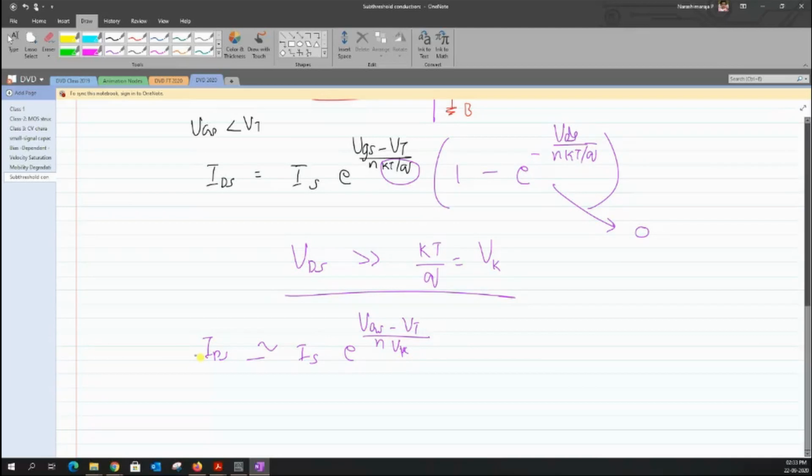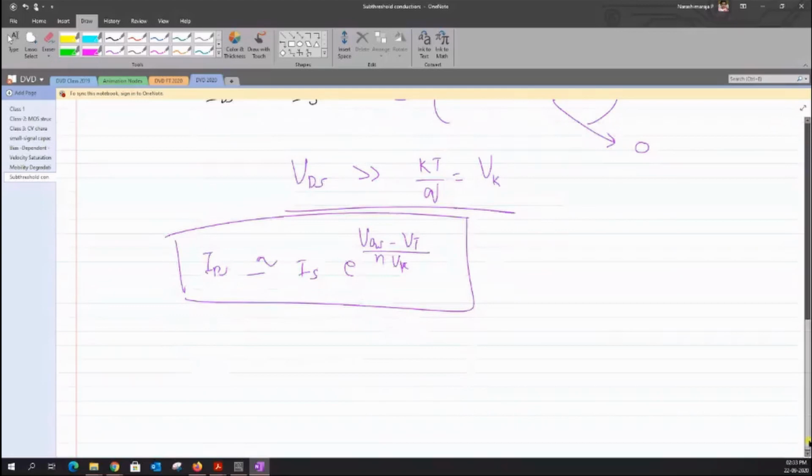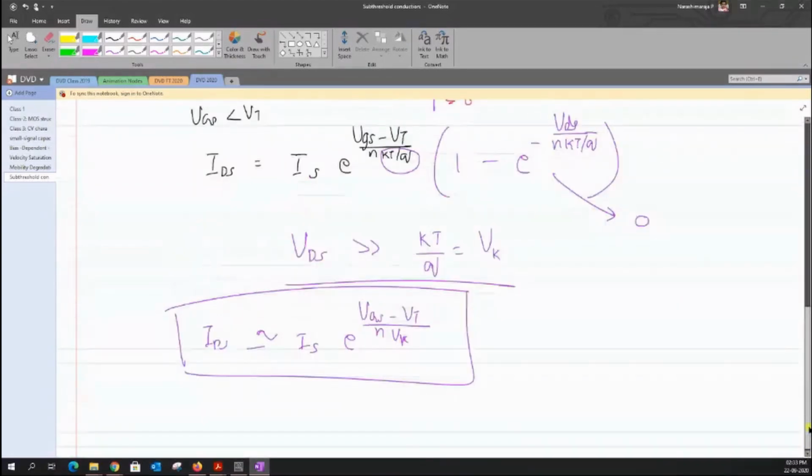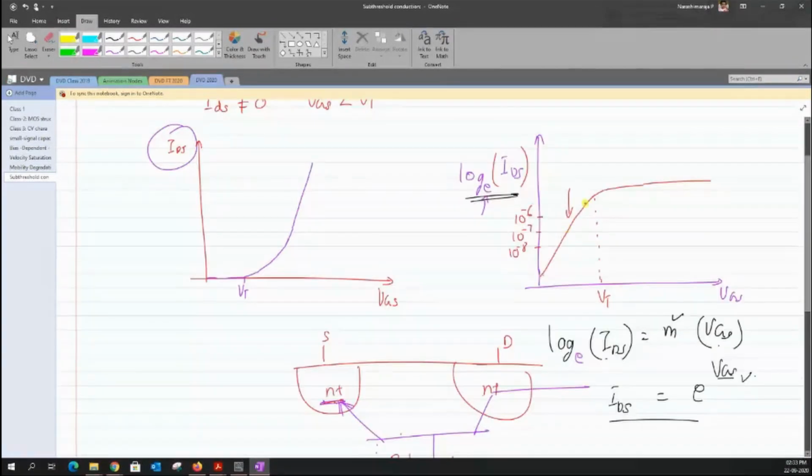Yeah, so this is the current flow, and now one could also want something out of this device, right? When I try to plot this particular curve, we will try to evaluate the slope factor. I want to evaluate the slope factor with something known as S, and I'll try to define it. We want to switch to the very lowest current at the earliest, so I want the slope to be much steeper. I want the current to decrease at a much faster rate. This is what we want to evaluate through this slope factor. The rate at which I'm trying to switch off is supposed to be much faster, so that can be read by the slope factor.